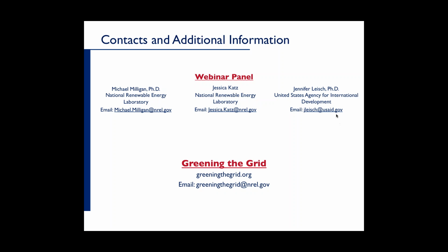Now, those don't come for free. So if you're moving from a slower dispatch, maybe hourly, maybe even a couple of hours, to a sub-hourly dispatch, there will be a need for increased tools to enhance system visibility so that you can see what's happening on the system. There may be a need for new computer hardware and software that can help do the faster economic dispatch. But those things are achievable. They may not always be easy, but I don't think you necessarily have to have a market structure in order to have a large balancing region and in order to do a fast economic dispatch.